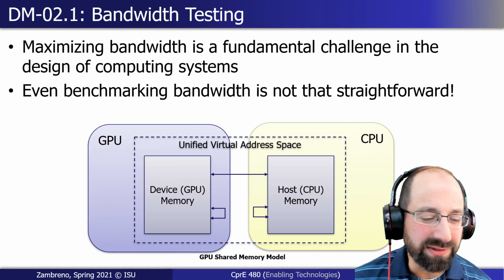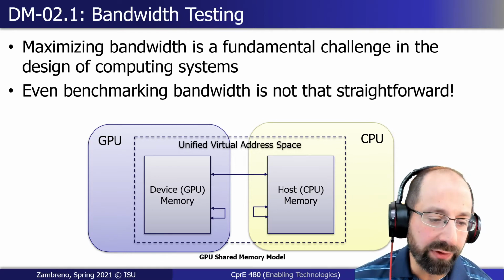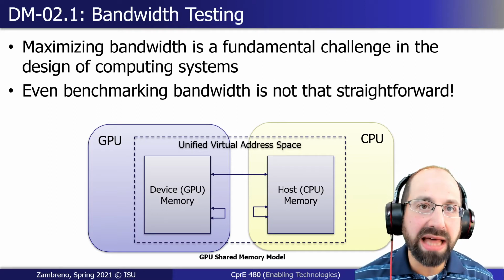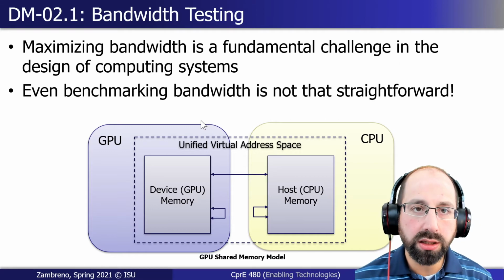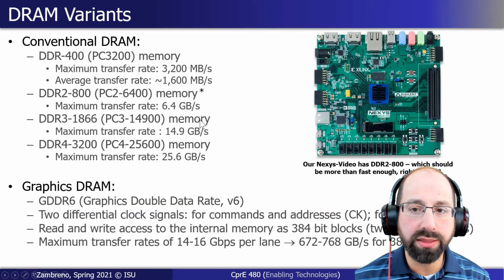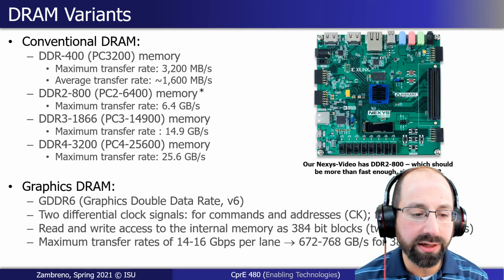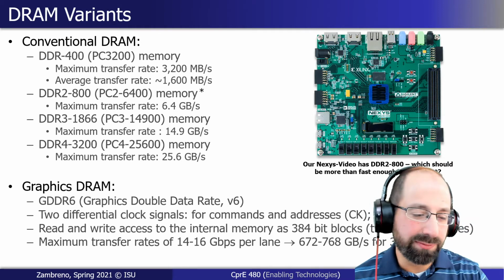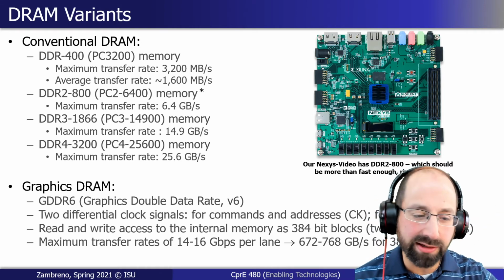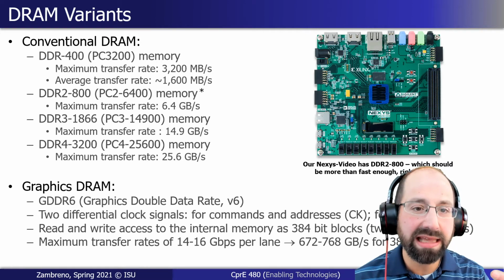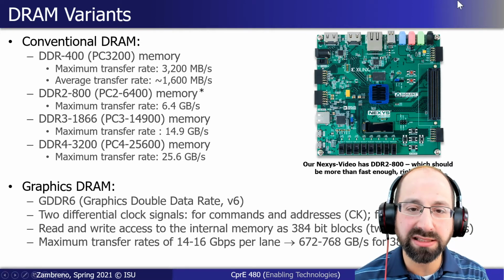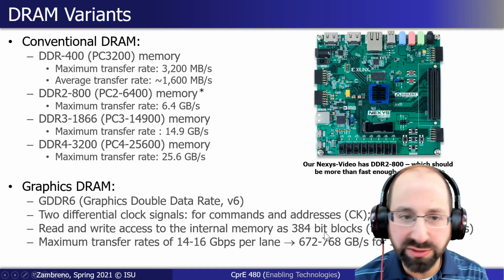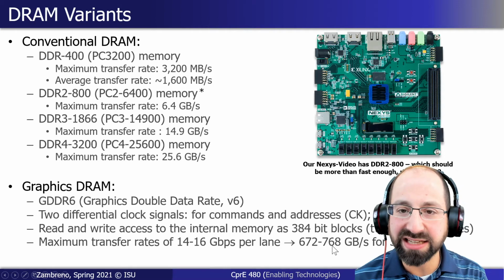Yeah, so when we talk about lanes of data in the DDR spec, and you could definitely take a look at it, basically each of them allows for an independent transfer of a single bit of data. So the actual math of what our theoretical throughput or bandwidth transfer rate out of a DDR system is: it's the clock rate, and then it's both positive and differential. So both on the rising and falling edge of that clock, you can transfer a bit of data, and then you have a certain number of lanes, and so you're basically just multiplying the given maximum clock rate times two times 384 to get that total number back out.